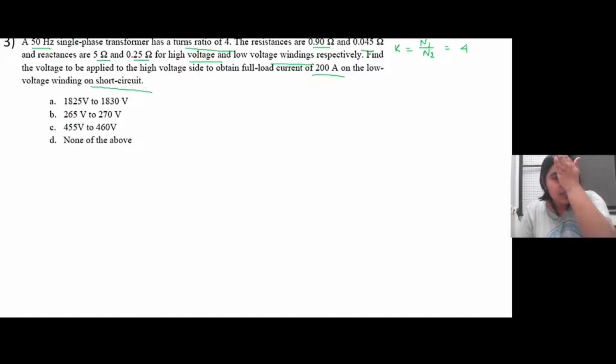circuit. So we have earlier seen that when the short circuit test is done on the transformer, we basically neglect the core losses and we calculate the copper losses, right? Because the core losses become almost negligible and can be neglected.